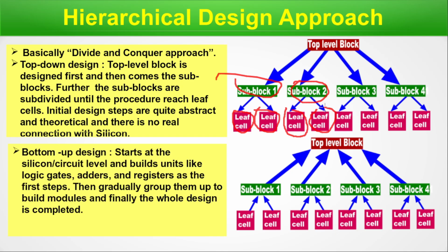The bottom-up design methodology starts at the silicon or circuit level and builds units like logic gates, adders, and registers as the first step. Then gradually we group them up to build modules, and finally the whole design is completed. It's just the opposite of the top-down design methodology.